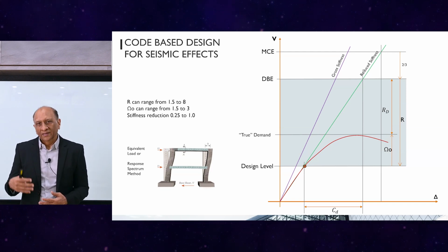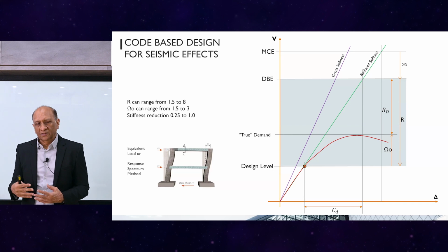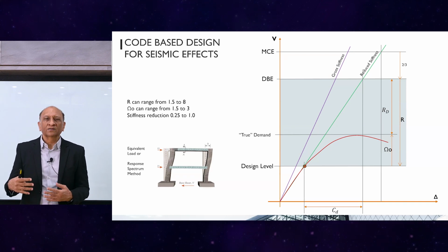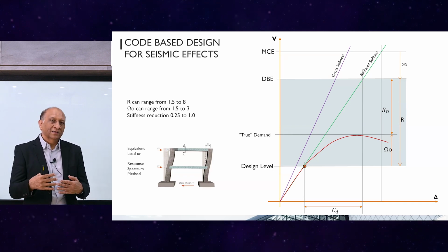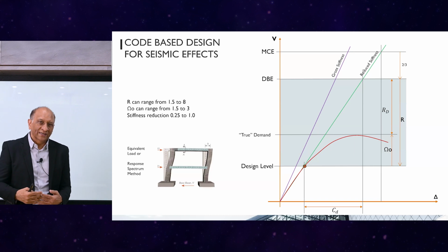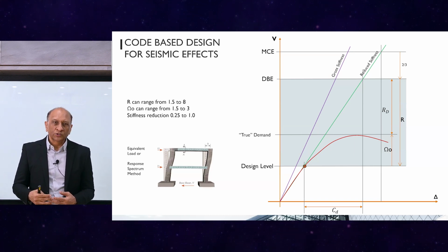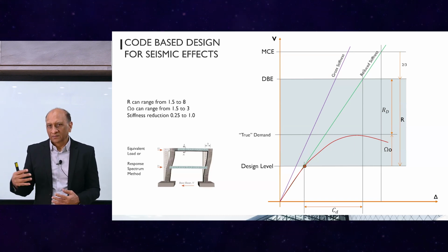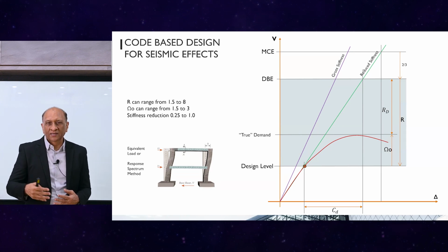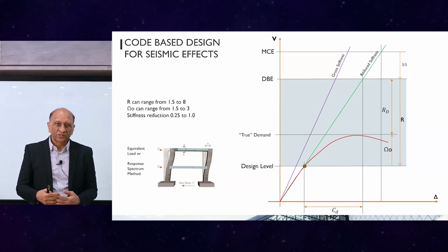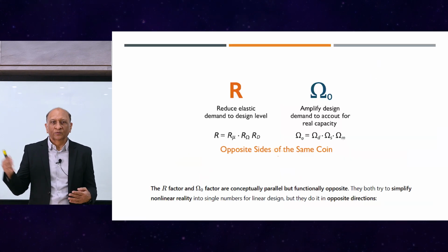Concrete also, if delivered by the concrete suppliers, is typically delivered higher than ordered because they don't want it to be rejected. This is based on sampling. So it's typically 30% more strength than the one ordered, once again increasing the actual strength in the structure, and the structure also gains strength over time.